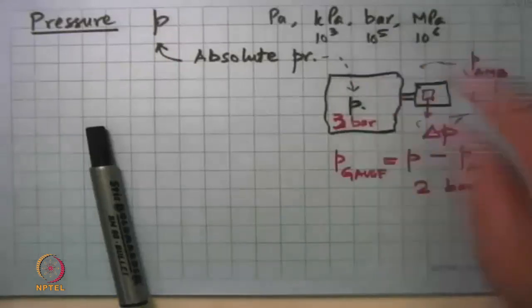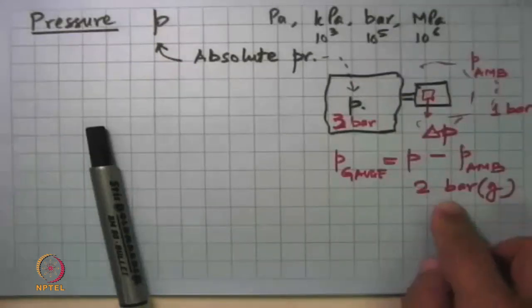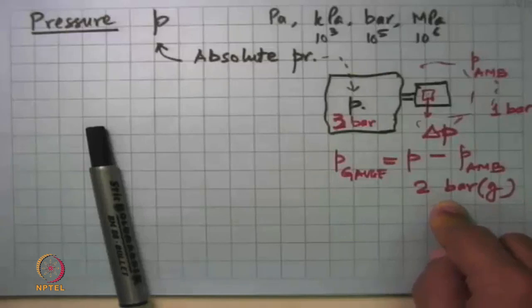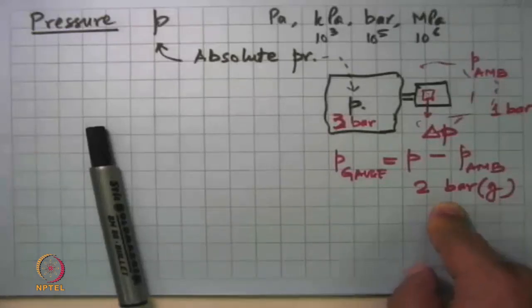So the tire pressure, whatever is told to us by the manufacturer and what we fill up wherever we go, we are always saying that what has been indicated by the manufacturer of the tire is a gauge pressure, and what the person is filling into your tire is also gauge pressure. And that's why the two have got to be the same.